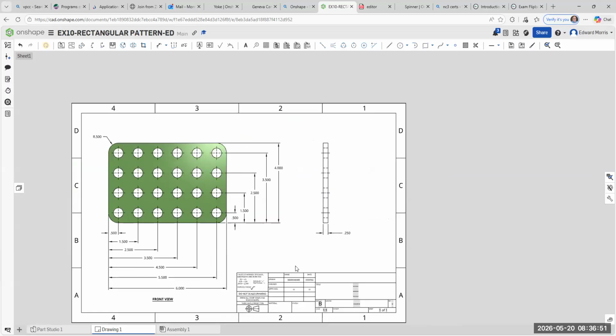All right. Now let's do that for the right side view. Go to the text. Click here. And we're going to type in RS VIEW. We're going to highlight it. Make it bold. Underline. Click on the green check mark. Hit escape. Now take your mouse, hold down the left mouse button, and reposition that label.